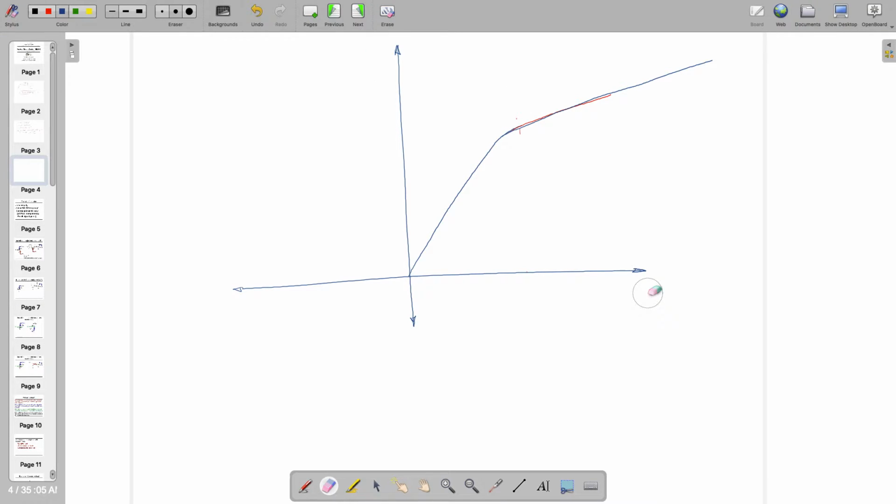We'll talk about something else, which is for MOSFET. In MOSFET, this also looks like this one. This is known as the VDS sat line, and this is actually equal to VGS minus VTH. For varying gate to source voltage and constant threshold voltage, this line will be there. And this is happening because of one reason.